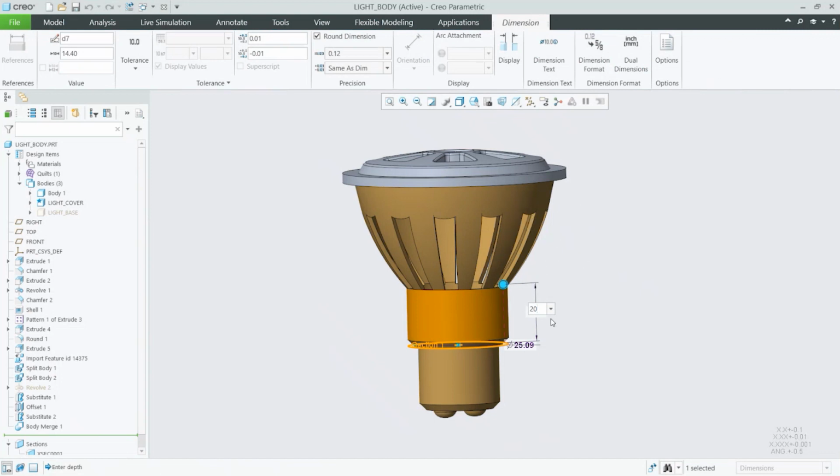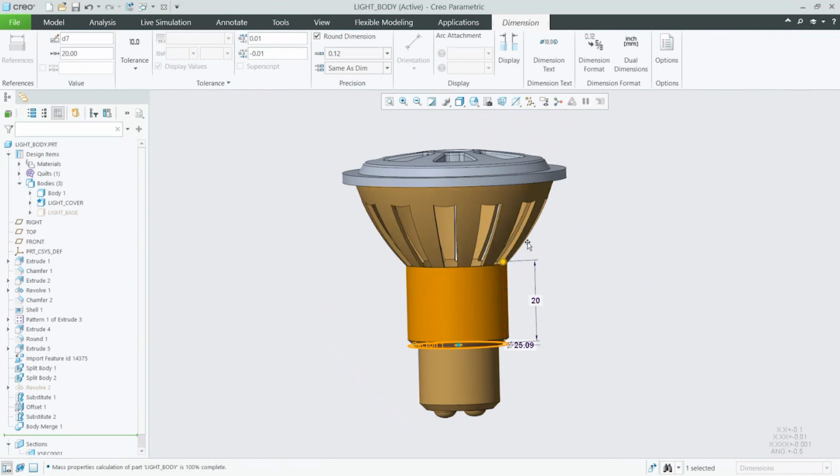Look at this shape. Enter. The top shape was destroyed. The top shape will change. See? It will change, because the reference is from the bottom for this example. So the parent and child relationship drives this feature to go up. Then the top surface or the shape will be changed accordingly.